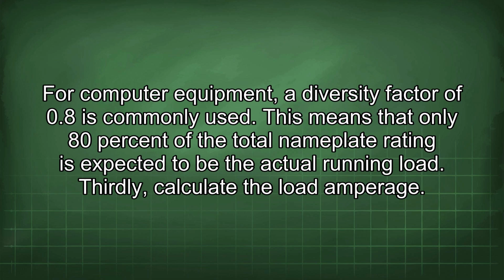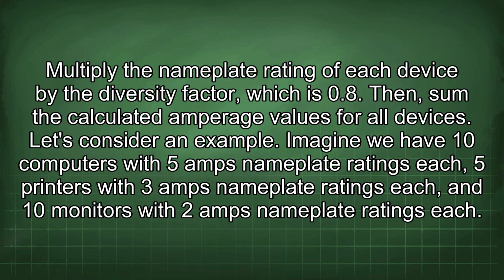Thirdly, calculate the load amperage. Multiply the nameplate rating of each device by the diversity factor, which is 0.8. Then sum the calculated amperage values for all devices.